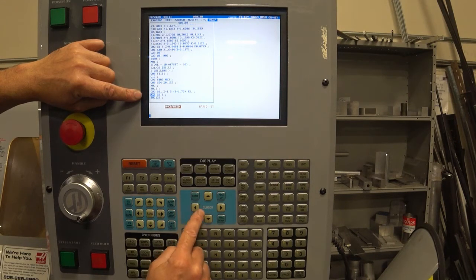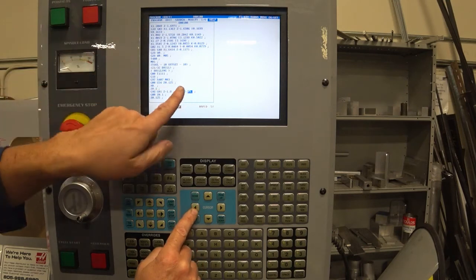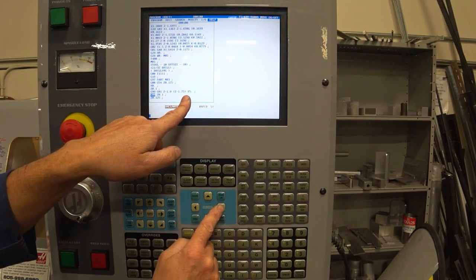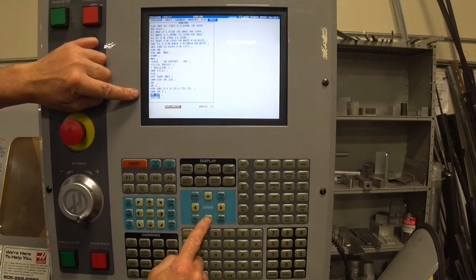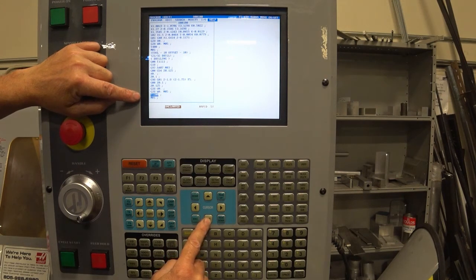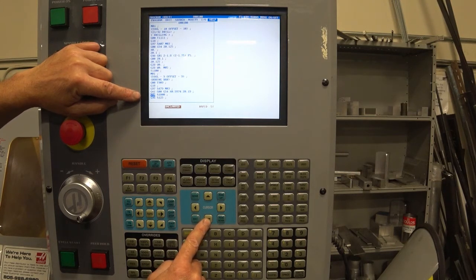This is controlled by the G98 G code. G98 and G99 control the way in which a lathe handles feed rates. Feed rates on a lathe most commonly are inches per rev, so that is the amount of travel of the tool per revolution of the spindle. However, a drilling tool is a centerline tool, and so the RPM and feed rate are fixed at fixed RPM and fixed inches per minute. And in this example, it's 5.